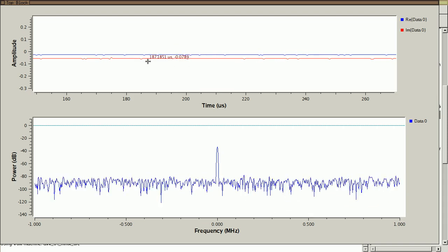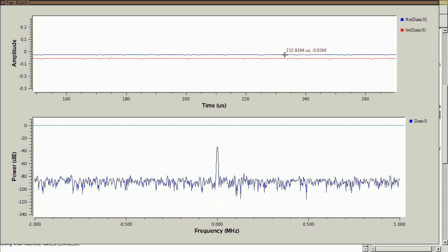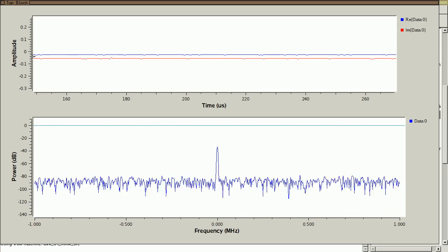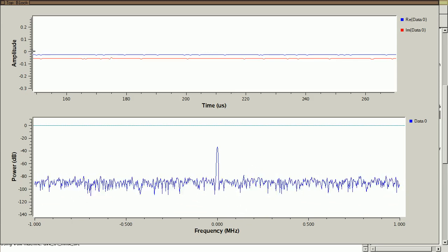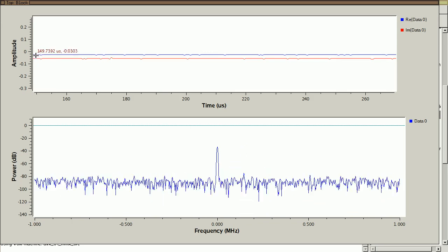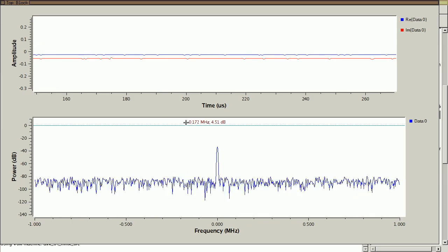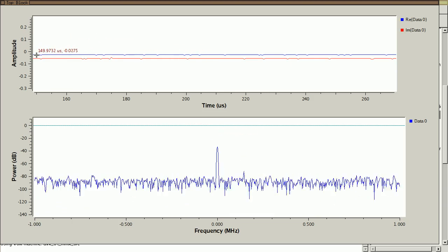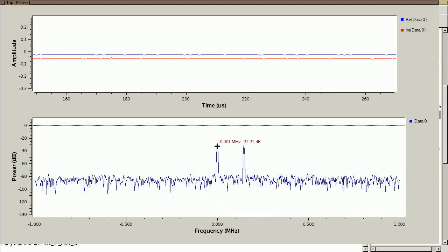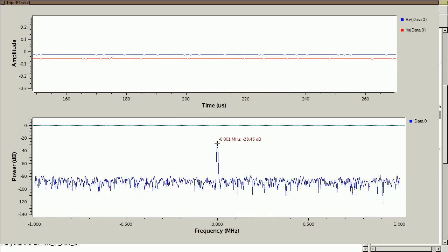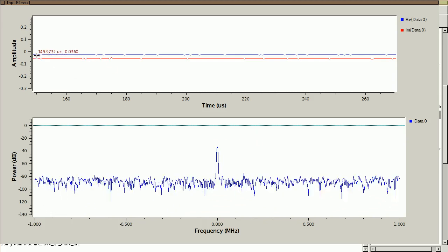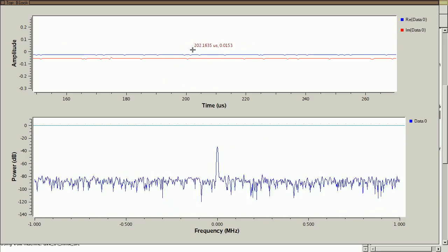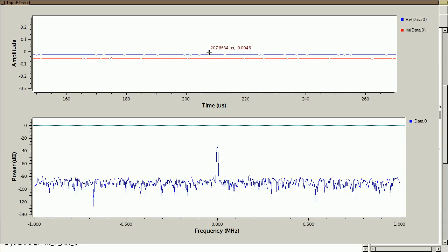And inspect a little bit this background noise here that happens between bursts of activity. Do you see how everything's between 0 and negative 0.1? It's offset from 0 a little bit, which is no big deal, but that's an explanation, and we'll talk about this later in a little more detail perhaps, but that's an explanation for this 0 hertz spike in the middle. There's some portion of the signal all the time that is a little bit off from 0. Now, that's perfectly normal in a receiver like HackRF to produce that type of a small defect.